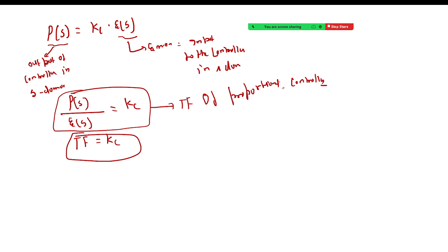Anyhow, and this is again, I'm writing all the same thing. But now here you can see there is a term Kc that has been written over here. In the process industry generally, this Kc is called the gain. Already I have written earlier. But in place of Kc in industry, you will see the term proportional band is used. That is defined as PB for the controller. Proportional band is used in place of Kc, in terms of gain, in the process industry, right? So how can we define that Kc?